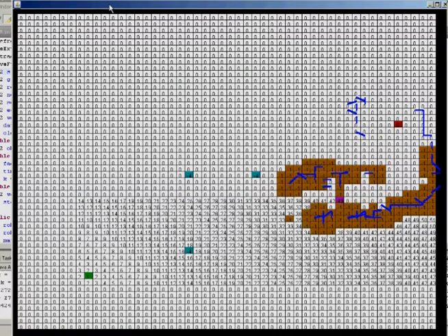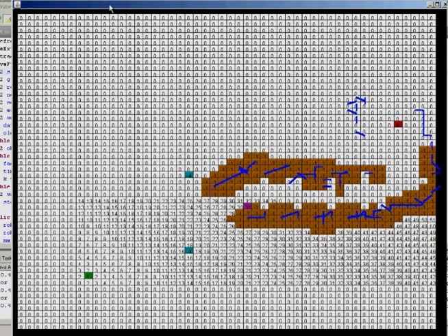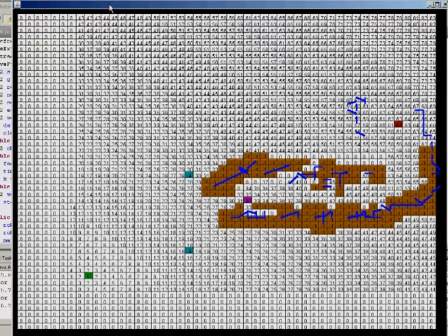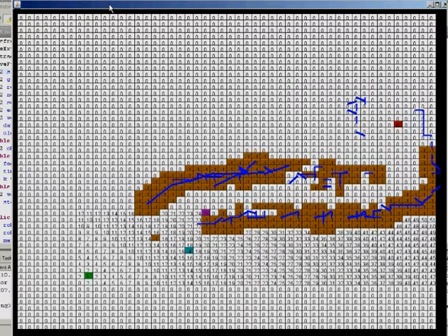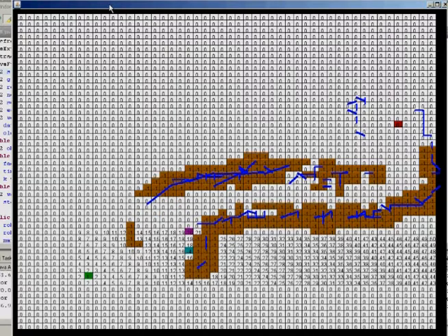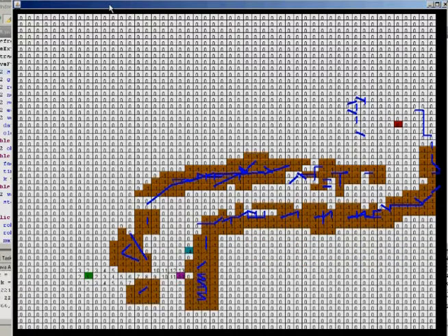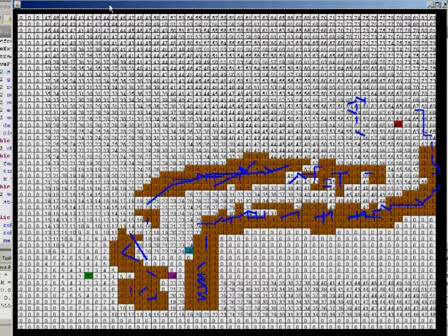Also, another thing about the actual robot is that the wheel is not steady or stable. Because of that, we needed to adjust the robot's orientation slightly, because sometimes it turned 110 degrees when we asked it to turn 90 degrees, and odometry thought it turned only 90 degrees. The reason is one of the wheels was loose, so it doesn't turn as much as the other wheel when it's supposed to. So that was the reason our odometry does not 100% replicate its actual location on the actual robot. However, if you just tweak that angle a little bit, it should be perfect.